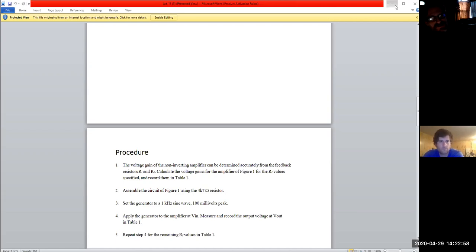So what would happen is the power supply looks at what the Zener has, and it does that with the comparator circuit. And if all things created equal, if they both balance out, boom, I get my output. But if the Zener gets popped and goes bad, and let's say the Zener is now kicking out some weird voltage or even a 0, when it goes into that comparator, what it's going to get out is craziness. And so it literally stops the whole power supply from working. And 9 times out of 10, that's your problem.